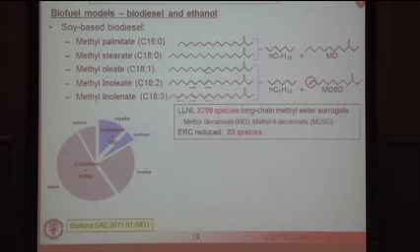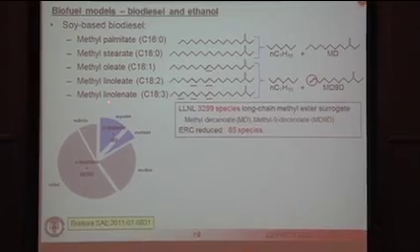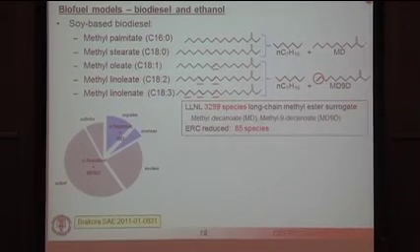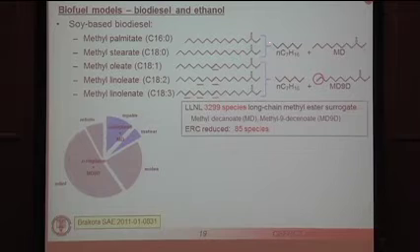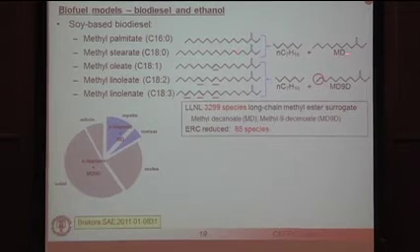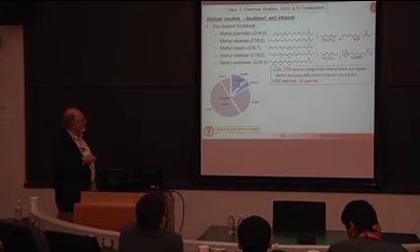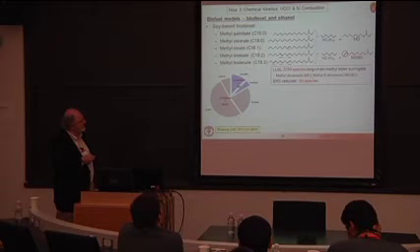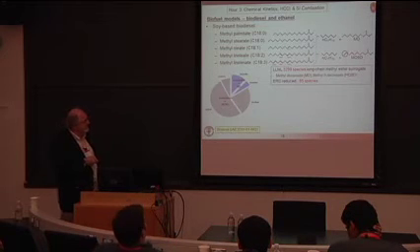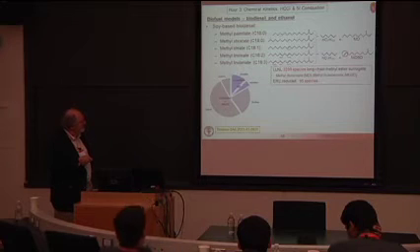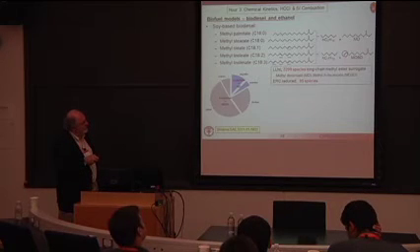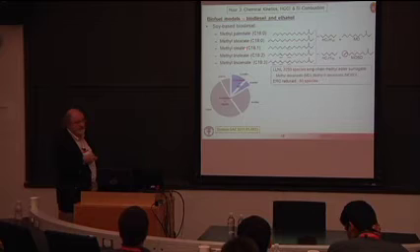So talking of the biofuels, there's a lot of interest in America in soy-based biofuels. Biodiesel consists of these 5 components here, primarily. What we do is we model the saturated components with the methyl decanoate mechanism from Lawrence Livermore, 3,300 species roughly. And then for the unsaturated components, we use the methyl decenoate mechanism. And so to represent a fuel like this, we would have essentially the N-heptane plus methyl decanoate, which gives us a C18 type of molecule.